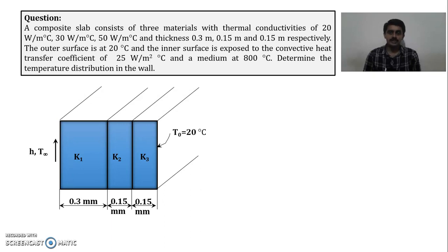The insulation has three layers, and you can observe the value of conductivity. The lower value of conductivity states a kind of insulation. When we observe the picture, throughout its length the scenario is the same. It is a steady state heat transfer and the heat transfer pattern is the same throughout its length. Hence, probably we can consider this as a one-dimensional heat transfer.